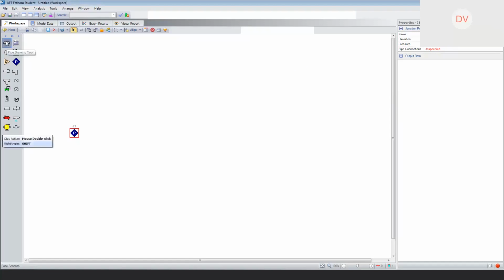So then we have the pipe. So it's just clicking on the pipe segment, adding the segment in, and then also you'll have your branch connection. So that's simply how you build it. So since we will have 12 segments of pipe, we will have P1 through P12, and then you'll have junctions, or the J's, up to 13, which include the very final one.